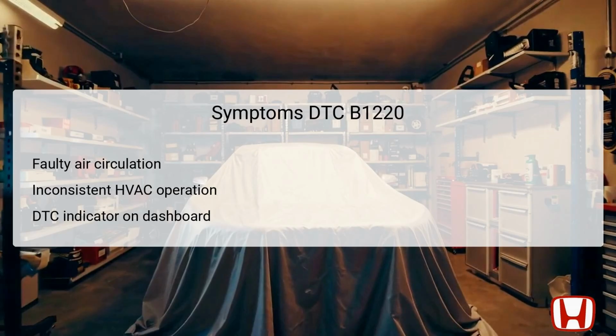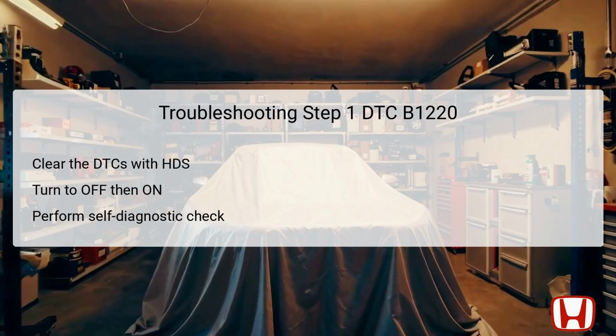The troubleshooting process for DTC B1220 begins with verifying the presence of the code itself. First, it is essential to clear the DTCs using the Honda Diagnostic System, HDS, which resets electronic controls and allows for a fresh start in diagnostics. Following this, the vehicle should be turned to the off lock position and then switched on again. This ensures that all systems boot up correctly.